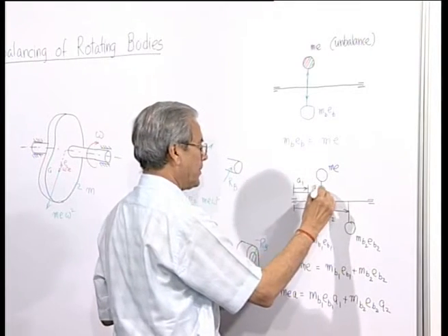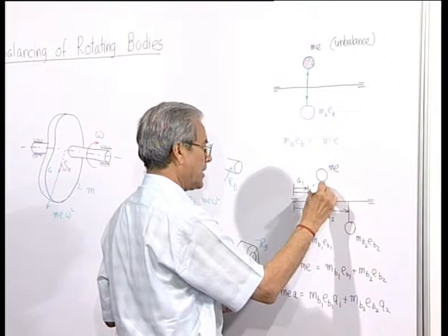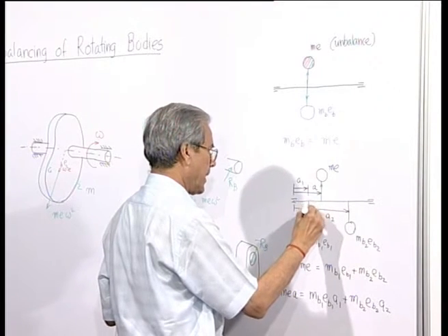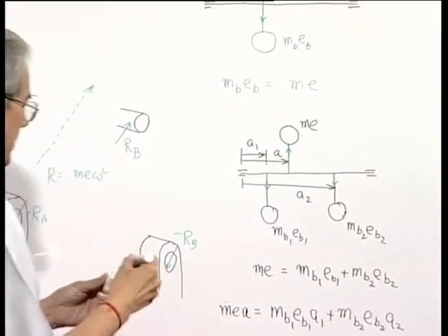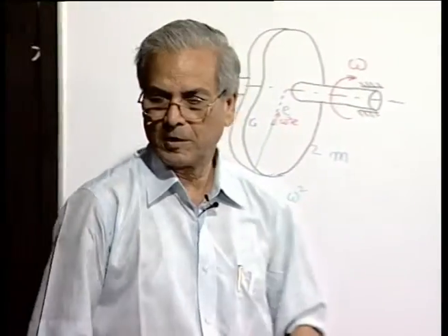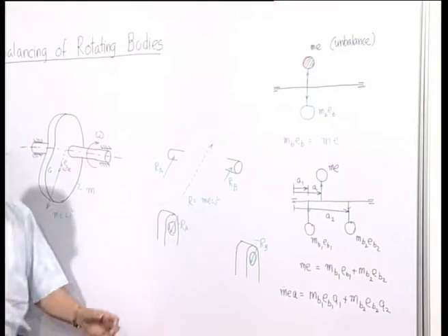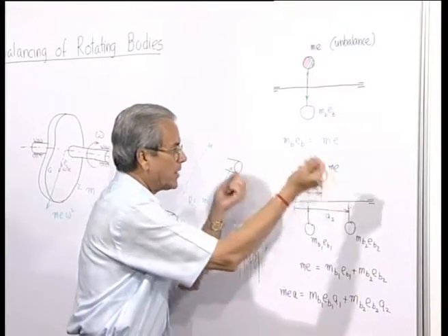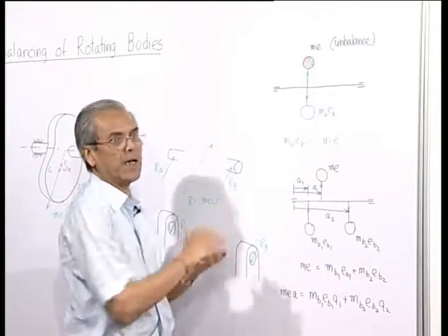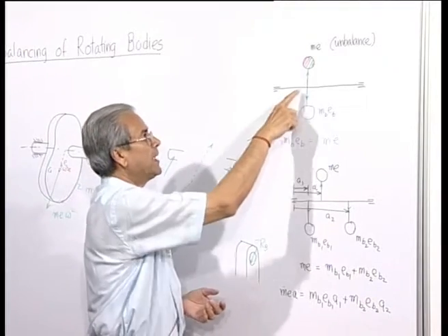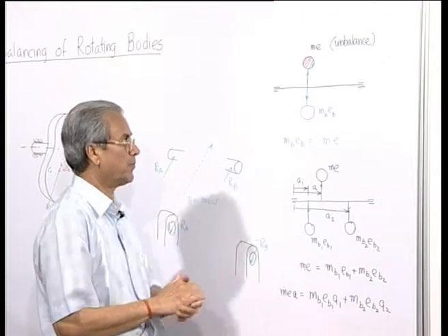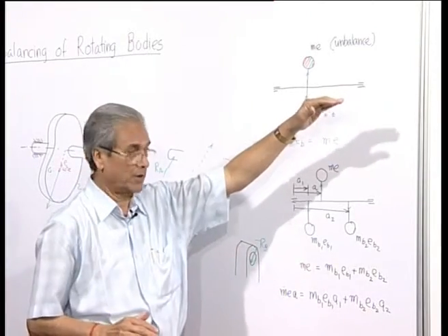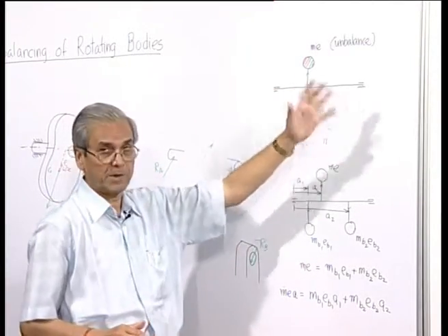In this case, the force which was here is neutralized by two forces like this. The difference is that, though so far as the supports are concerned both will be free from dynamic forces, in the earlier case the shaft is completely free from any effect due to the centrifugal forces. There will be no bending moment or stress to which this shaft will be subjected.